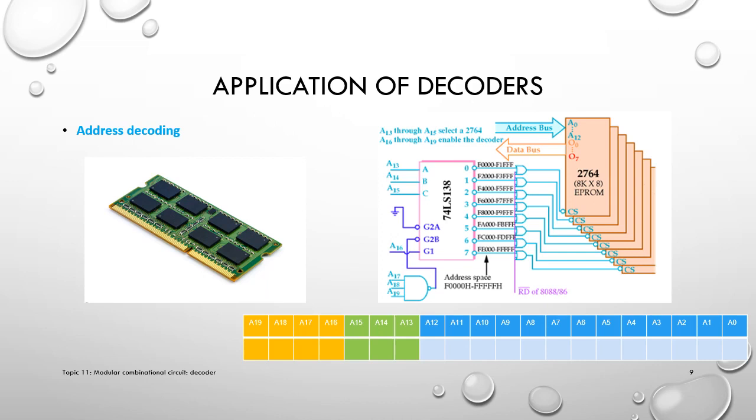There are fixed data stored in those memories, and many times we need to read data from these memory chips. But how do we accurately find the right data to read? That's the problem here, because we have so many chips, and in each chip we have 8K different locations, and in each location we can store 8-bit data.